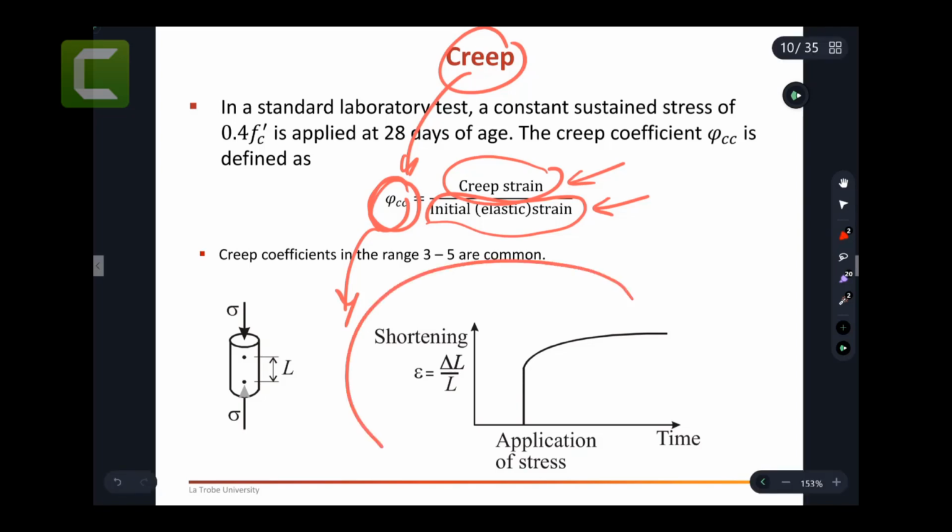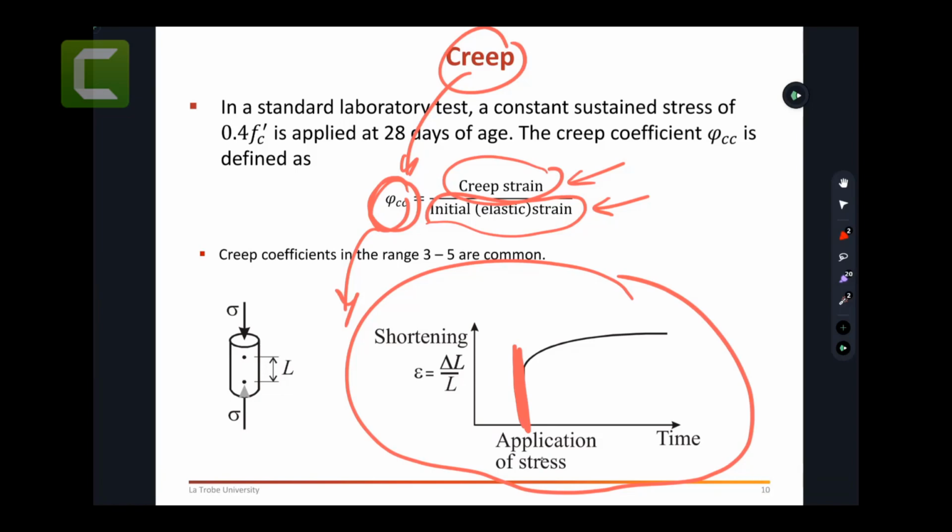Now, I was talking about this curve previously. Usually, the first stresses a beam is going to take are by the time you strip and take away the scaffold from under the slab or the propping components.